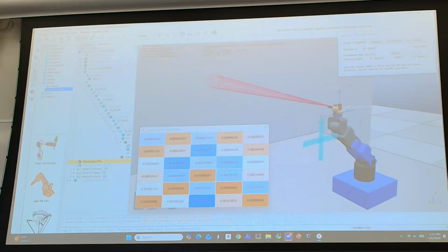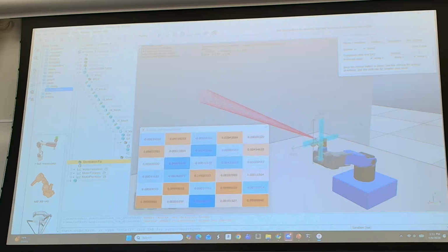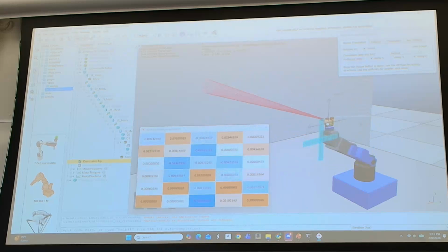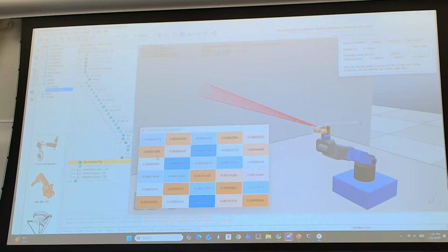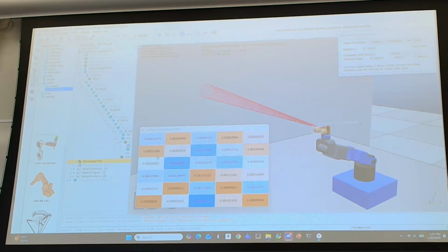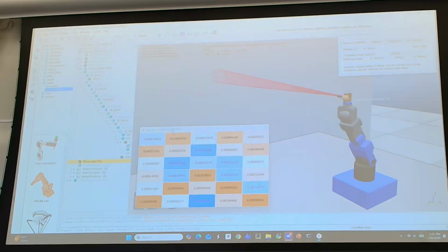Like I said, I think I'll go ahead and make a planar robot arm for you guys, and then we'll maybe do a 2 or 3 joint arm. And then we'll take the Jacobian that we saw right there, the very simple planar one, because all it is is a twist. We saw how it works, but we'll put the planar one together because I think it's easier. Where we can say, look, this is where it's at, and my Jacobian theta 1 happens to be this, theta 2 is this, and theta 3 is that. And we'll see when we perform that Jacobian that that's exactly why we're getting these relationships, these values, to see it for real.